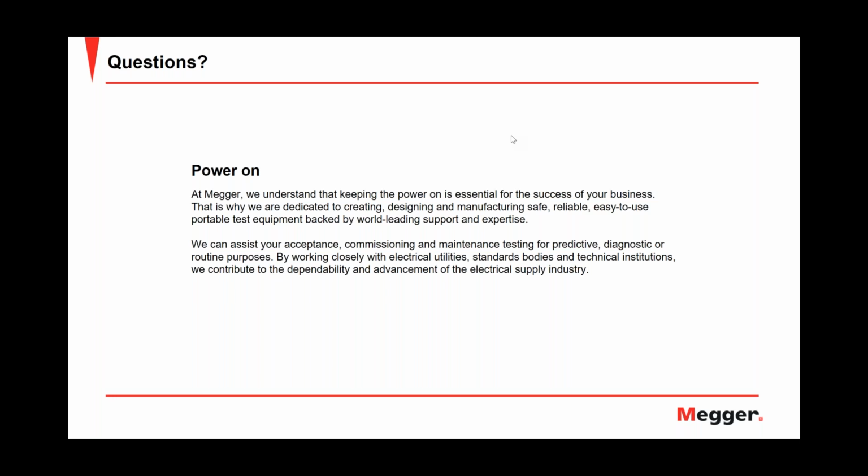That is a DC voltage. So pretty much all the fault location equipment has a DC source in there, which you could call a cap charger. It's a source to charge the cap, but it's also used as a DC high pot function. And this test, as Javier explained, is carried out as a ramp test.